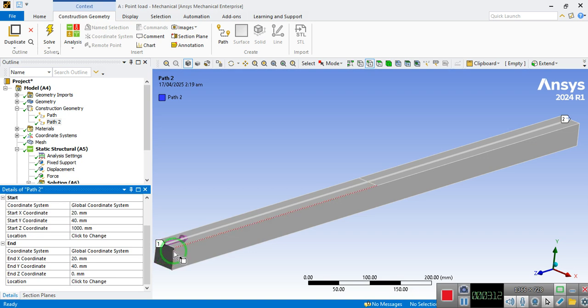So I know that this is a 40 mm cross section. The x coordinate is 20 mm, because I guess the triad is here, so 20 mm, that's fine. If it's 20 mm here, then at the bottom at the neutral axis it will also be 20, so this will not change.